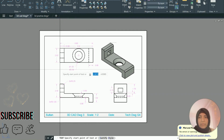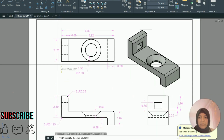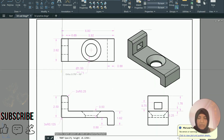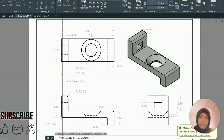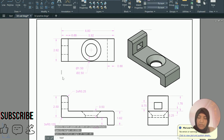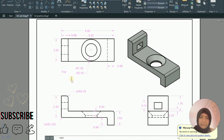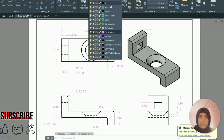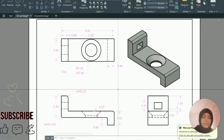Single line text, composite starting left edge of the object, and then if your height is different than 0.125, then type 0.125. If it is 0.125, just enter, and then 0, yes, enter, and then type top. So I need to make that in annotation text.